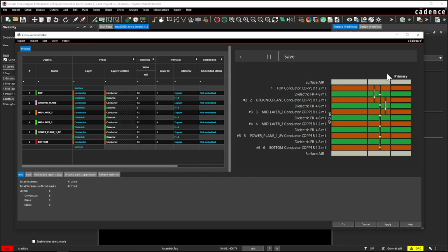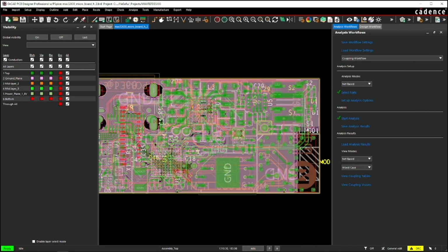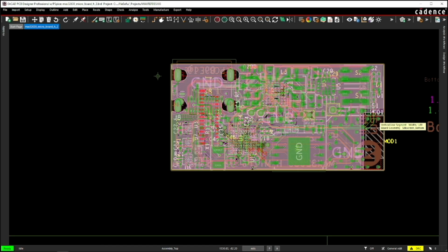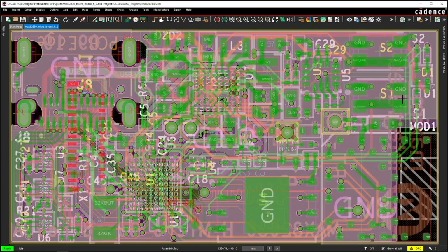You also need to take care of any special mounting configurations. Let's say your design is going into a different mechanical environment. Also double check placement of components when reusing a design. Cost can also be a factor. Let's say you're not able to do a 6-layer PCB in the amount of quantities that you would really want. So if you have limited quantity for manufacturing and you can only do 4 layers, then how do you redesign your reference design to accommodate fewer or more layers?